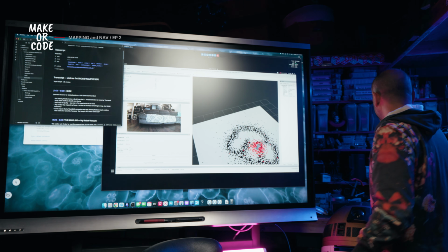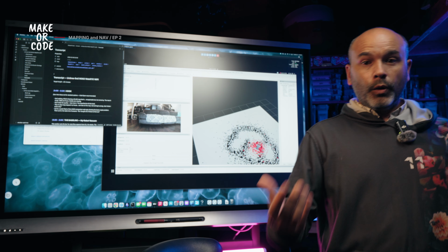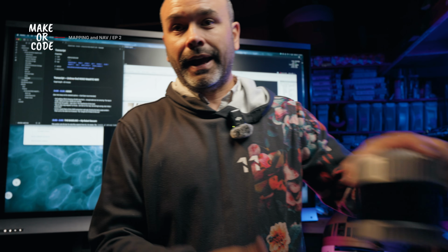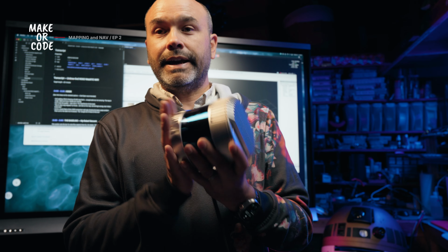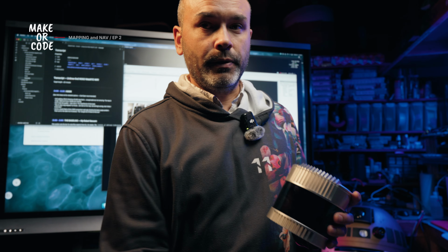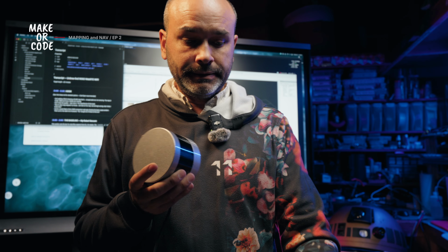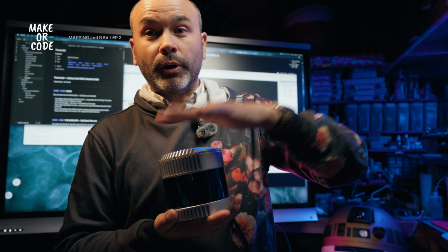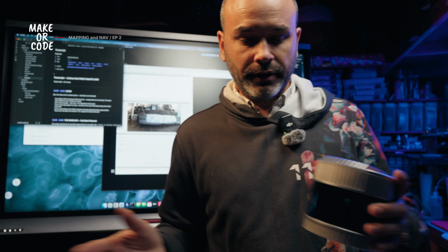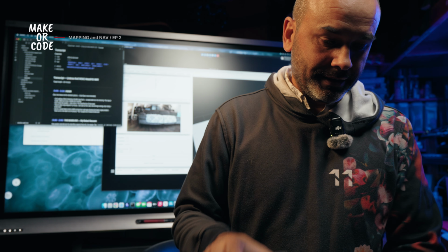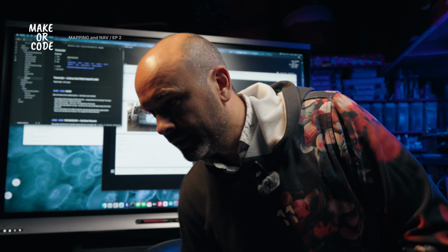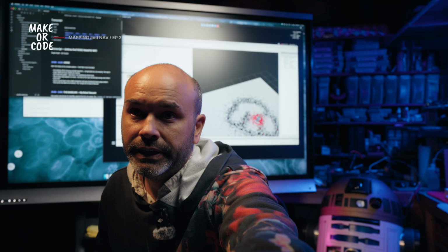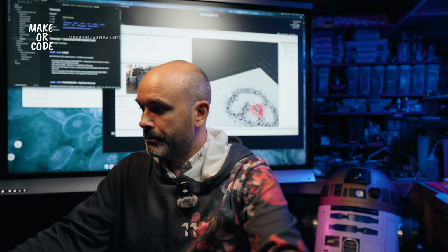So that's the next plan of attack in this, is to see what I get out of using a VLP-16 or a Pandar mounted on top. This guy's heavy, almost double the weight of this VLP-16, but this only outputs 16 lines, where this one outputs 40 lines, so I will get a better density, as you saw in the plots. So yes, I will make it so that I can run them both, but I'm running on to the limits of what the Unitree Go2's payload is, so I may have to worry about that.